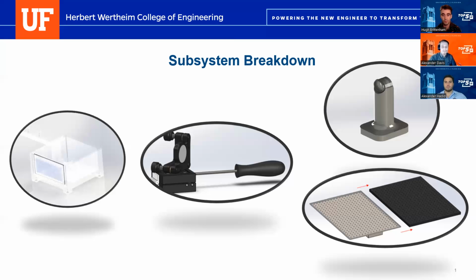The mounting subsystem is designed to house the required lens and mirror components required to complete the laser beam dimensional manipulation before hitting the zebrafish. The mounts come equipped with magnets embedded within their base, allowing them to be easily placed and removed from the magnetic optics table. The mounts are able to magnetize to the table through the use of a sheet metal attachment that covers the top surface of the optics table breadboard.